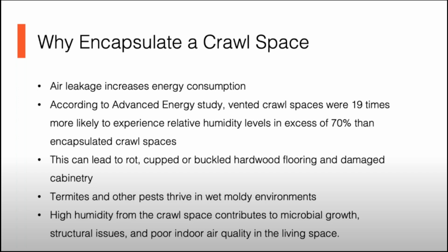According to Advanced Energy, homes with vented crawlspaces are 19 times more likely to experience high relative humidity levels in excess of 70%. This can lead to a lot of rot, cupping, and buckling of hardwood flooring, and even damage to cabinetry. Again, if it's hot and humid outside and we're bringing in that air below, we're causing a lot of damage below the home. That is ultimately going to go into the house.